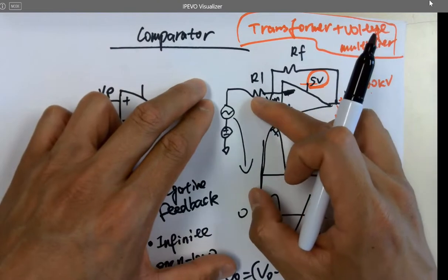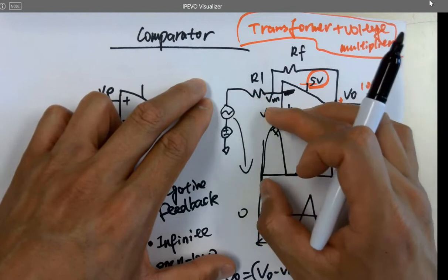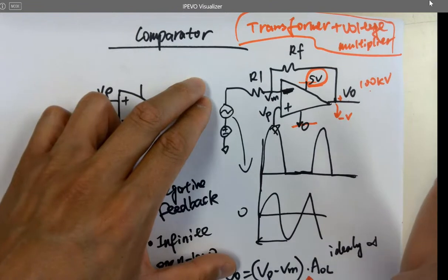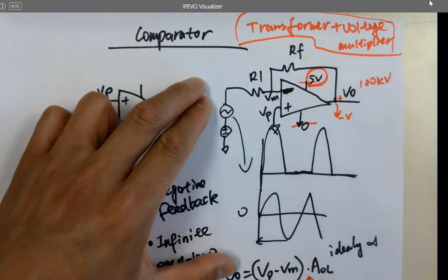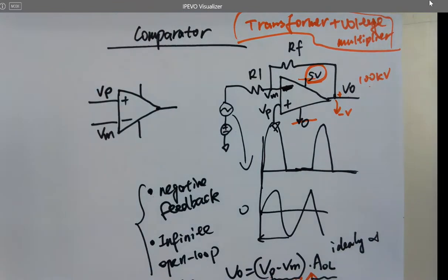Sometimes you just want to amplify by twice or 3 times or 10 times. And usually you do not amplify it by more than 10, 20 times, because it also amplifies the DC offset and the noise as well. So you want to amplify like 10 times, filter out the noise, and then amplify again. So have multiple stages of OpAmps in the real world.